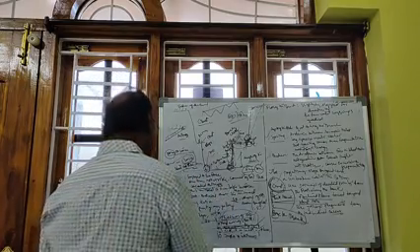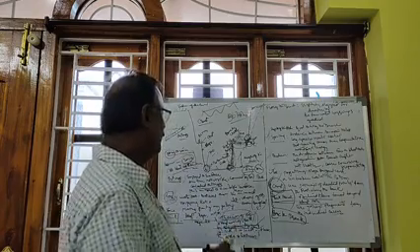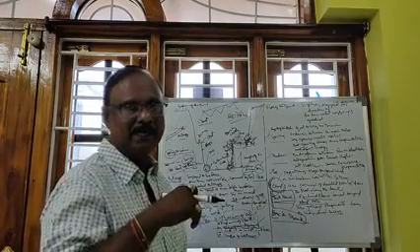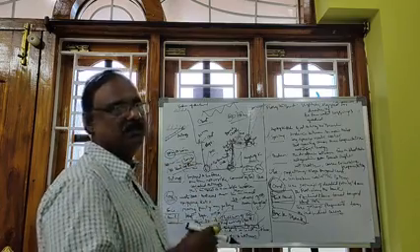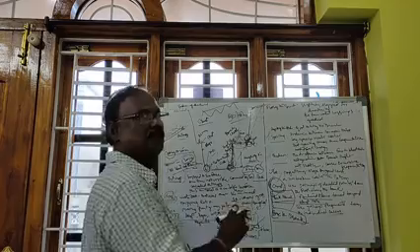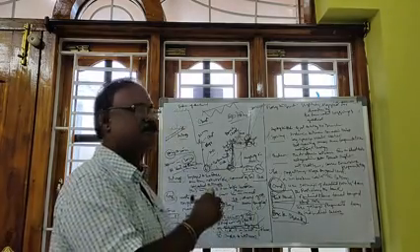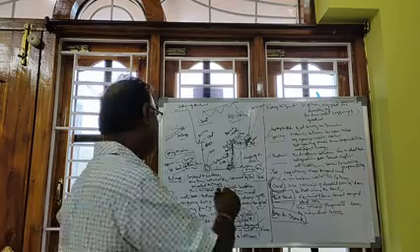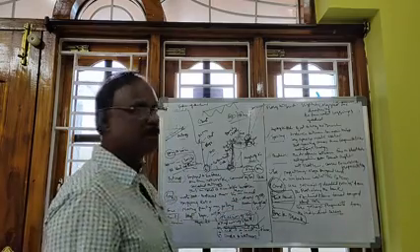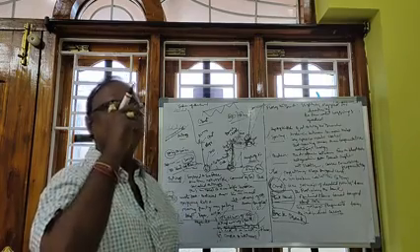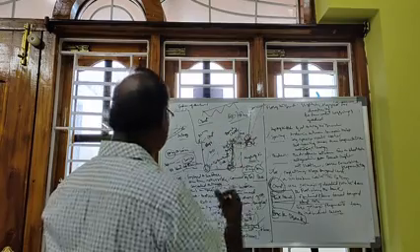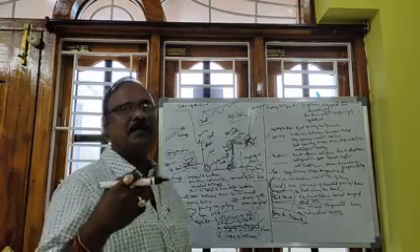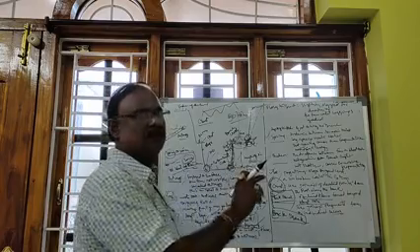The factors which influence the height of the bench are the thickness of the overburden, the hardness of the strata, equipment size, the range of mechanization, the nature of the bedding plane, and the degree of wetness. So these are the different factors which influence the bench height. In this class we discussed a number of terms associated with open cast mining. From the box cut onwards, suppose the mineral is available at 50 meters, so we lay the box cut.